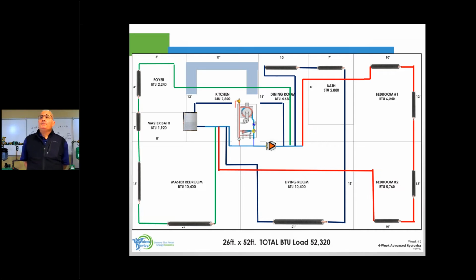Even with the panel rad there, that still may not be a comfortable room. I may want to warm that floor with some radiant tubing. I can run a combination of maybe the panel rad and some floor warming to make sure I keep the room to temperature. And when I'm near the front of that kitchen, where there's probably going to be some glass, and I've got cabinet in front of me, glass in front of me, a tile floor, no heat below, but my mechanical is under there. And if I'm standing there in bare feet, that could be an uncomfortable floor. So we could do a combination of the panel rad and floor warming, or if the budget doesn't allow, maybe just a straight panel rad to do the heating for that room, or just a straight radiant option.